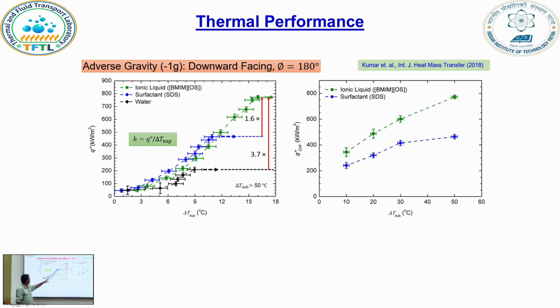With water, you will reach dry out at 220 watts per centimeter square, and that too because you have bubble departure from the sides, big bubble departure, right? Because we have only the heater, but still we cannot get rid of the gravity. So eventually those big bubbles will be so big that they will depart from the side. So essentially speaking, this number is practically 0.